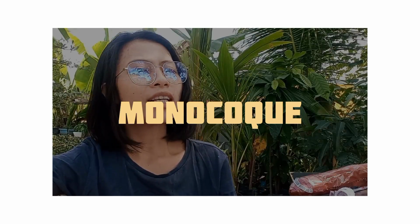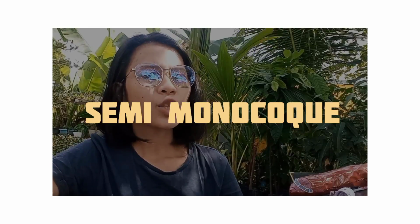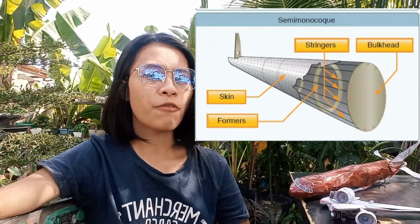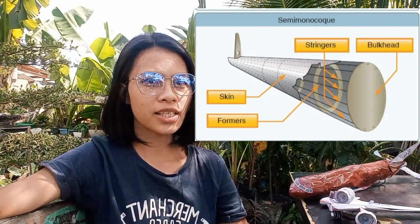Second is monocoque. It uses stress skin to support almost all loads. It is very strong but not highly tolerant to deformation of the surface. Third is semi-monocoque. It uses substructure which consists of bulkheads and formers of various sizes and stringers.